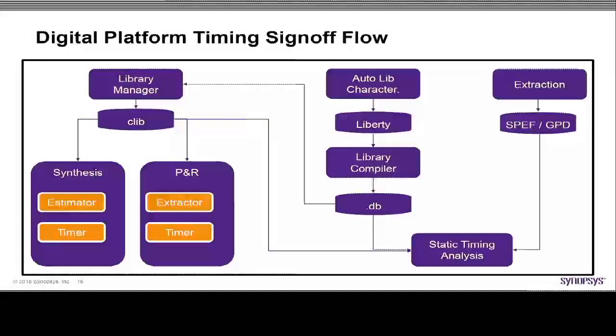Here, what I'm trying to stress is the timing sign-off. This is the classical CMOS, and we're doing the same timing sign-off methodology for superconducting electronics. It's a little trickier than what you might think. It's not a matter of having a .lib file with proper timing characterization and just taking a critical path and summing up the delays with budgets for corners and so on. It is much more involved than that because of what I mentioned in terms of arrival times, of concurrent pulses, and so on. So this is in a nutshell.